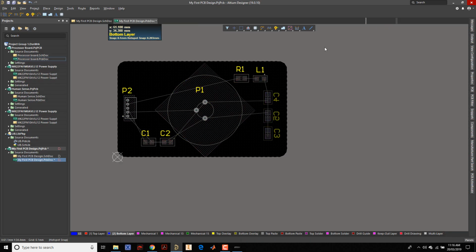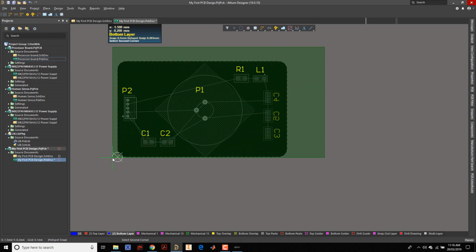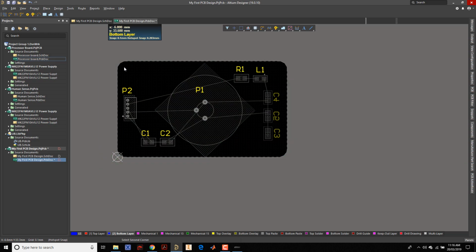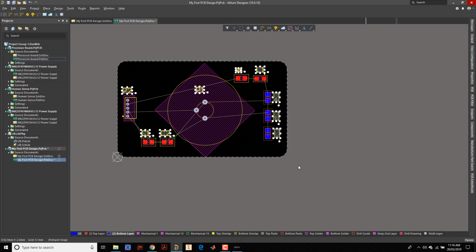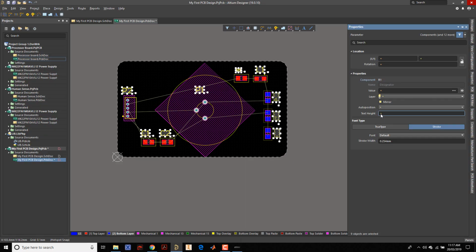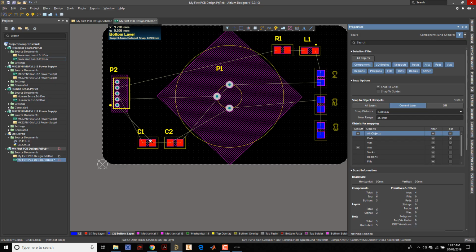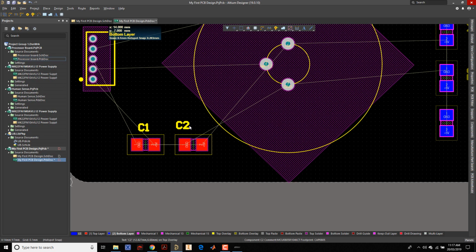So I want to edit all at once. I'll highlight it and then set the height to 0.8. If I press Control A, it highlights everything. I'll go to properties and set the text height to 0.8. See, it edits everything and makes it look nice. Okay, good.